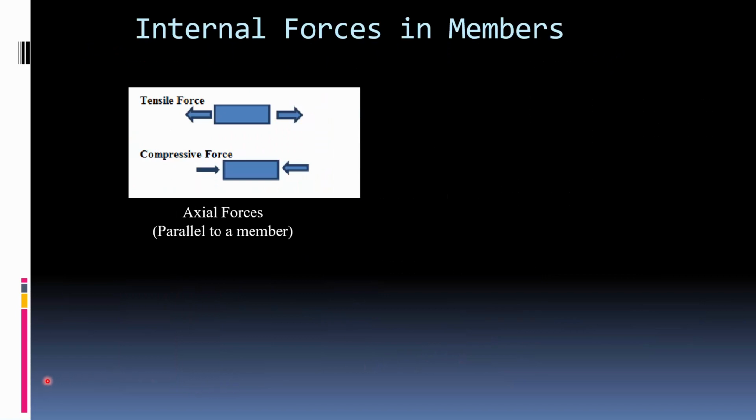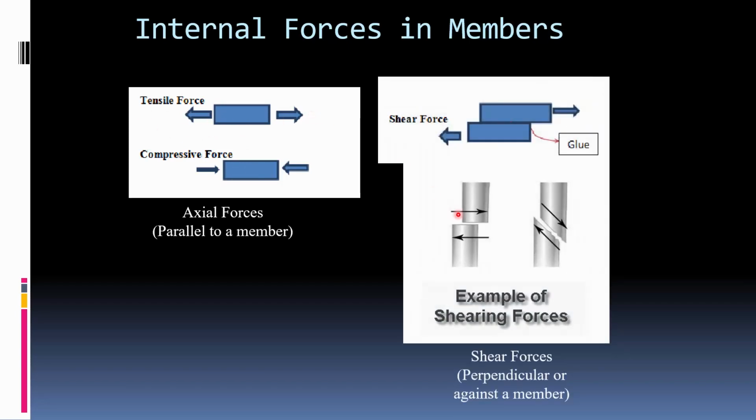Okay, so what are we talking about with internal forces? So these are the axial forces, right? You cut it off, you have some either tensile forces or compressive forces, things pulling it apart, pushing it together. They're along the axis of the item. Shear forces, what are shear forces? Well, say you have a couple pieces glued together and there's a force here and here. It's the force that's trying to tear these things apart. Or say you have an object like this. It's a force trying to break it in half, or here, the force is shearing it apart, tearing it apart.